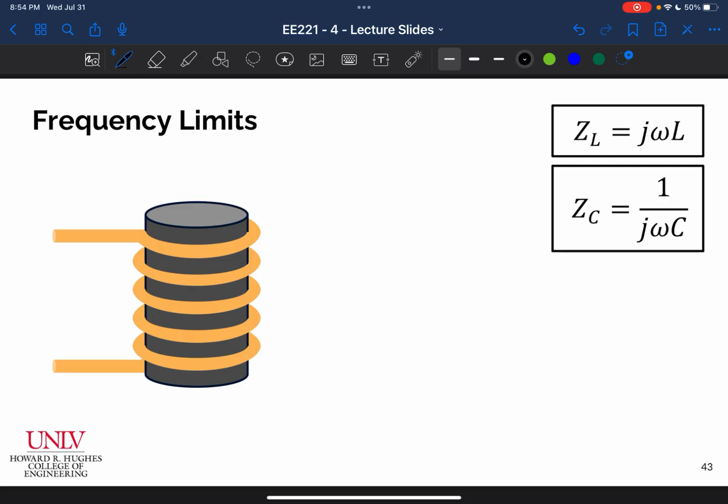And so what we could say is that this wire is ideal. And so the component, if we were to draw it in an electrical schematic, would just look like an inductor. But in reality, we know that there is some length associated with this wire. There's some cross-sectional area associated with this wire. And unless this is a superconducting material, we know there is some resistivity, even if it's copper. So we might say that even though this is a really good conductor, it has, let's say, 20 milliohms of resistance, then we can't neglect that in some cases. We have to actually take that into account.